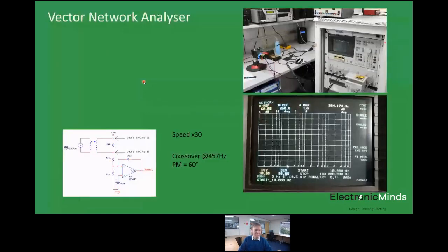The traditional way we have gone about measuring loops is, you imagine that buck converter I showed you a few slides ago, where we have our integral control error amplifier here. What we end up doing is we put a small resistor, 10 or 20 ohms, something like that, in series with the high side resistor, and we couple a swept sinusoidal signal into that resistor to create a disturbance in the control loop. So really, we're injecting a disturbance in the control loop and then measuring the response of the control loop to that disturbance, which, if we do that over frequency, gives us our loop gain.